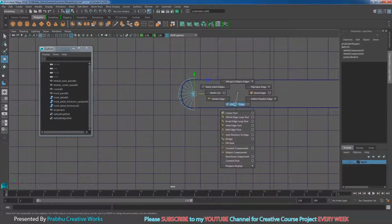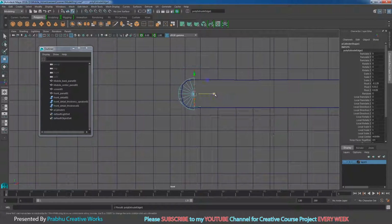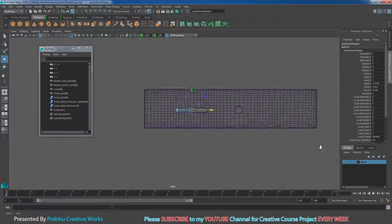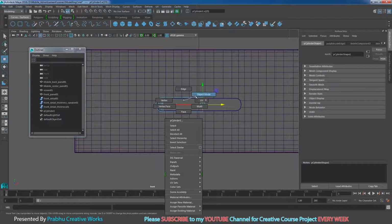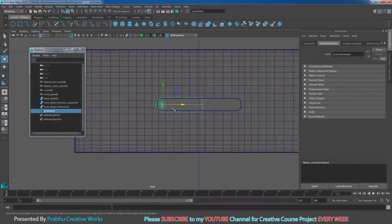Shift right click and choose extrude edge and press W. You want to move over here on center. So I will move a little bit in X. So right click and choose object mode. So I will select this object.